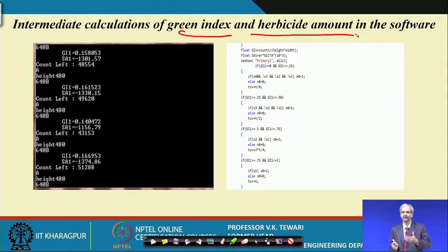before you instruct these solenoid valves for application, and ultimately the chemical will fall on the rollers. Since the rollers are being pulled in between the rows, they will smear, and the chemical will ooze out onto the weeds, and those weeds after 48 hours or so will simply be killed. They will not revive. In the meantime, your crop revives and then the crop grows.